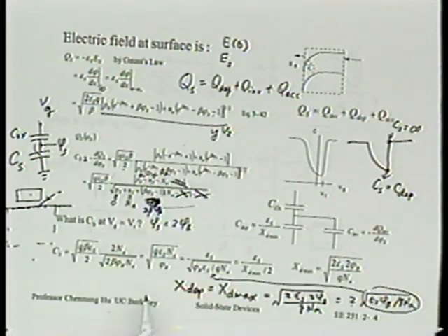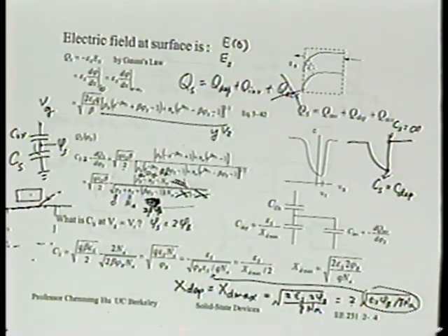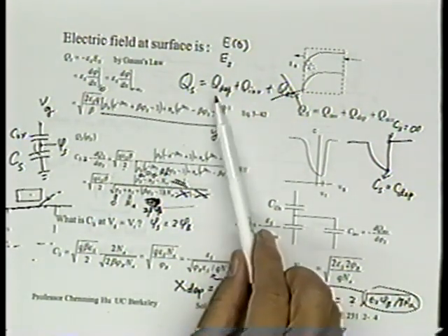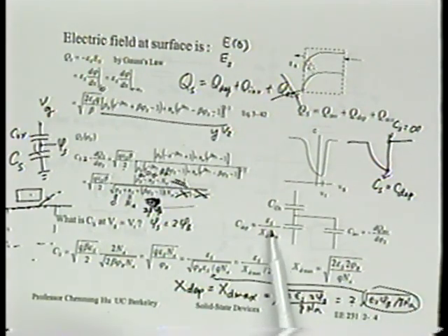In this particular example, the third component truly is negligible. But neither of the first two terms is negligible, right? So we have to bring them in. And the first term, when we differentiate that, we're going to get the usual, what you would expect, epsilon s over xd max. So that concept is not wrong. What you have in mind is correct, that the depletion layer will give us capacitance. The value is epsilon s over xd max, and that's just fine.